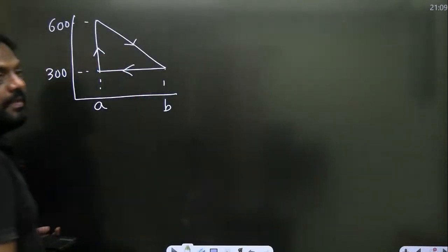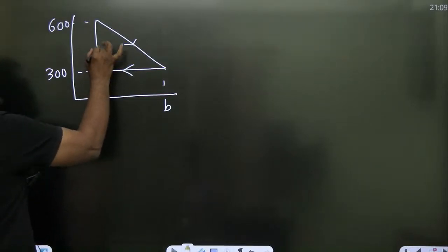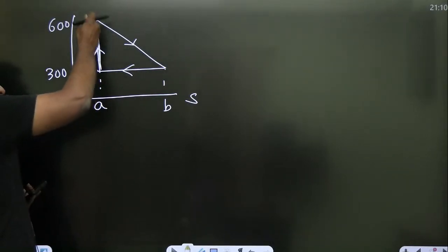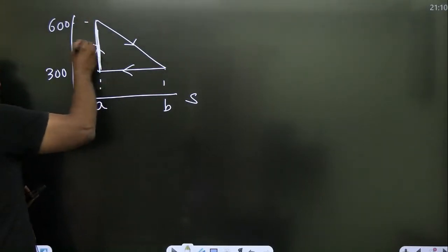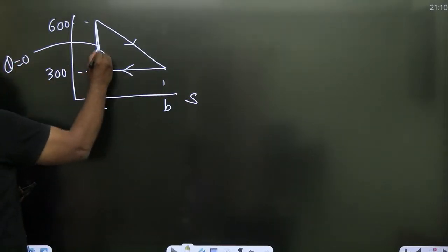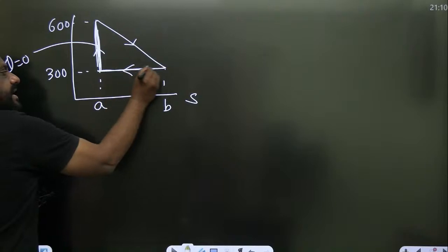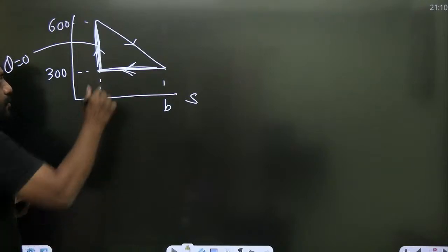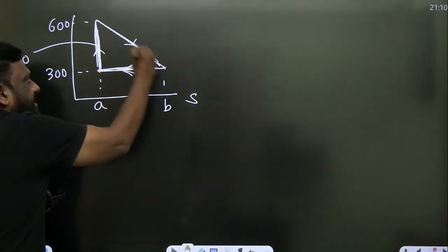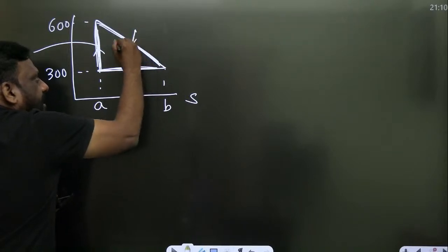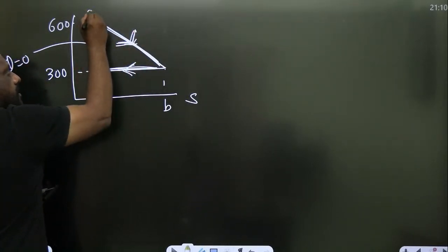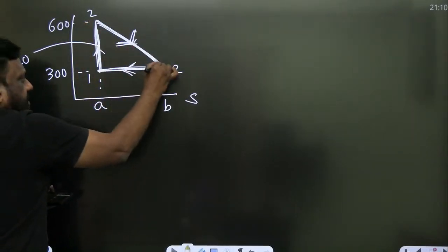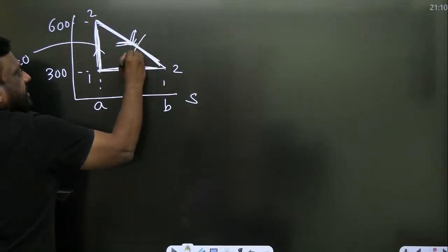इधर देखो सर. Now, what is this process representing? It is isentropic, reversible adiabatic. तो इसमें heat transfer zero है. Heat transfer is zero because it is reversible adiabatic. In this, entropy is decreasing. Entropy decrease means heat rejection. In this, entropy is increasing. इसमें entropy बढ़ रहा है. That means from this to this, let this be 1, 2, 3. So in this, entropy is increasing means there is a heat supply.